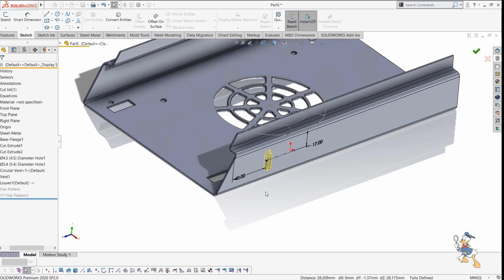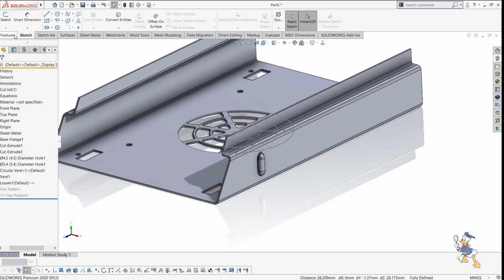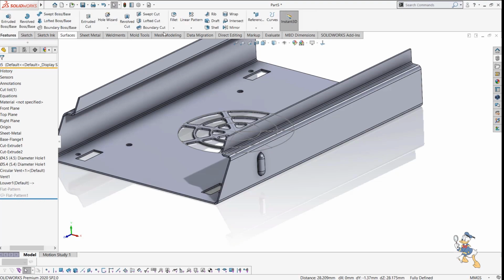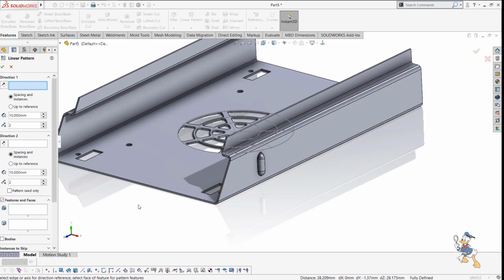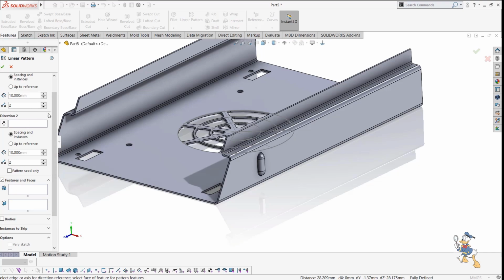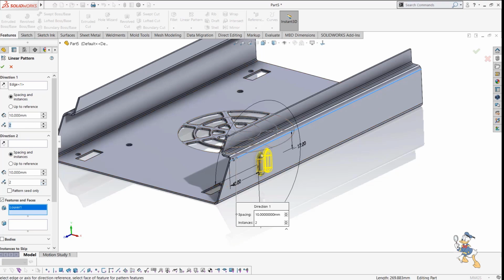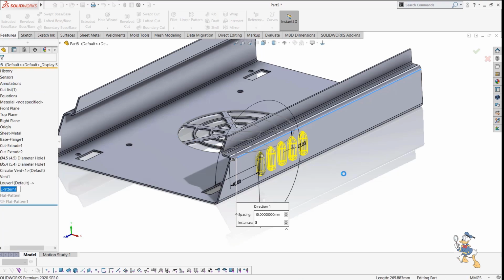So it is very easy to design this kind of stuff in SolidWorks, and it is very helpful while designing sheet metal components, because we struggle while designing sheet metal components. We need to think how we can design, and we need to concentrate on improving the design itself. If we are focusing on how to make our tools in SolidWorks or in design software, it is a very time-taking process. SolidWorks reduces our time because it is very user-friendly software, and we just need to provide the details in a very simple manner. Like I just need to generate some louvers over here with a pattern distance of 15 mm, and then I just need to check it out. It is very simple to generate this kind of stuff in SolidWorks.